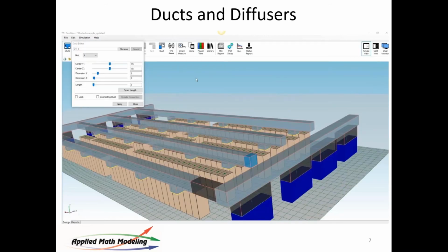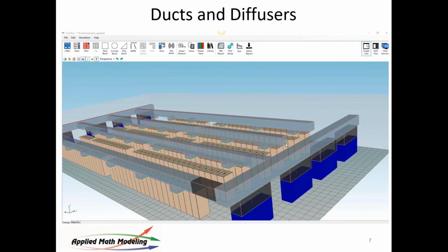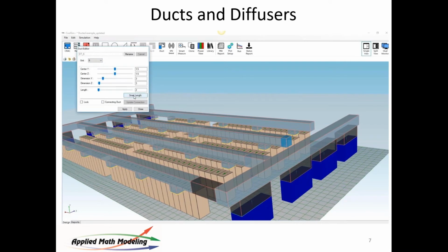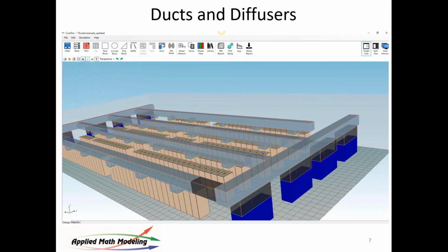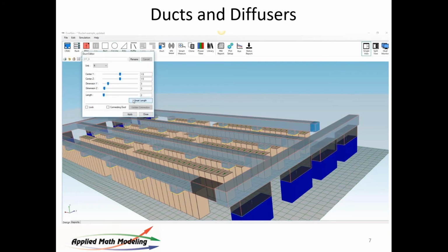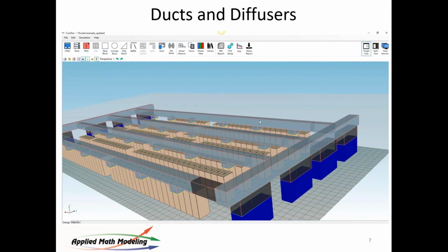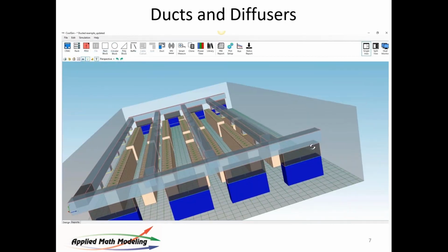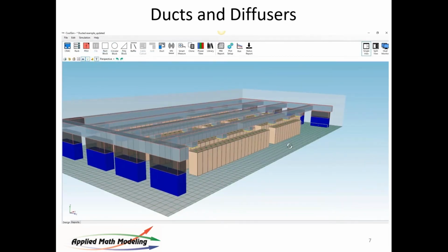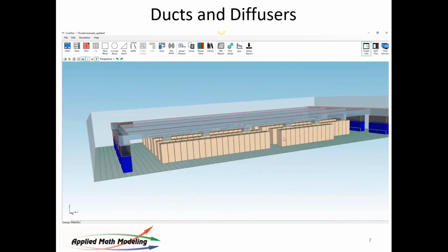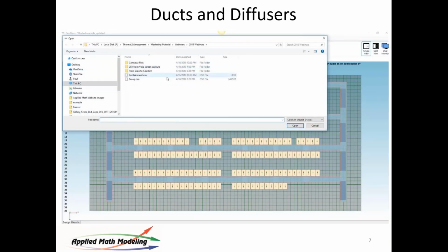So there I've added my subducts, connecting ducts. And now I'm using Smart Link again because I'm adding a subduct to the end of this guy right here. Add duct, it protrudes it. I hit Smart Link, boom, connect it. So now I'm connecting these by adding a subduct to the end. Add duct, right mouse click, add duct, Smart Link, boom. I connected the first one using connecting duct, or I can just put another duct on it and use Smart Link. So there's my room, pretty nice.